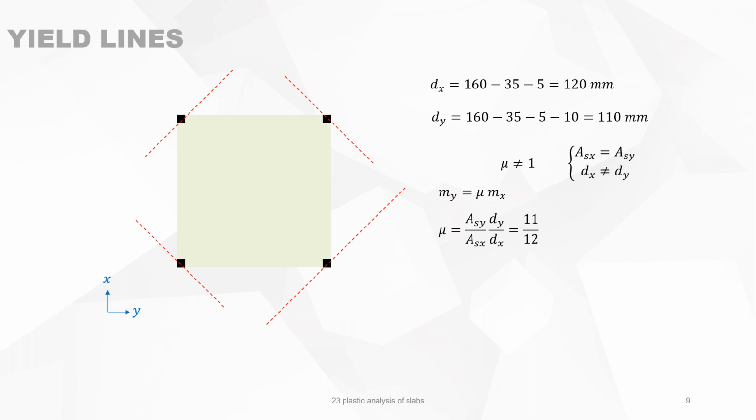Then we look at the axis of rotation. We have taken them at 45 degrees because of the symmetrical situation of our problem. In reality, you should call this angle alpha. You should make the calculation, and then you should optimize your problem according to alpha to find the maximum bending moment. But because of the symmetry, we know that alpha will be 45 degrees.